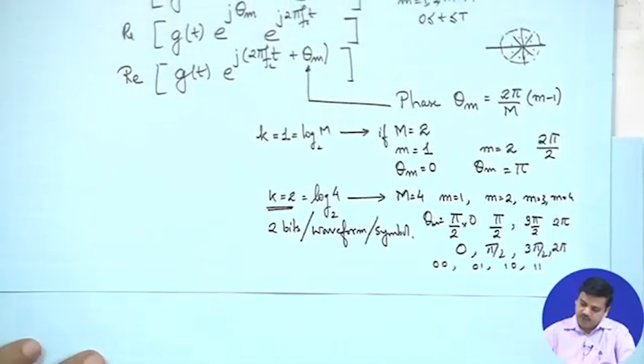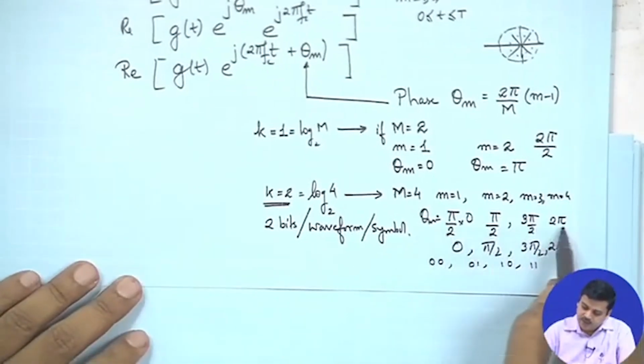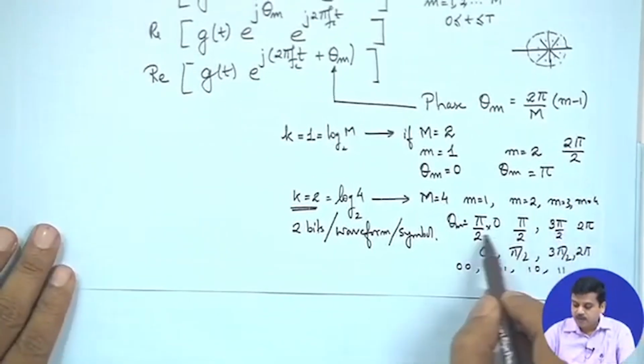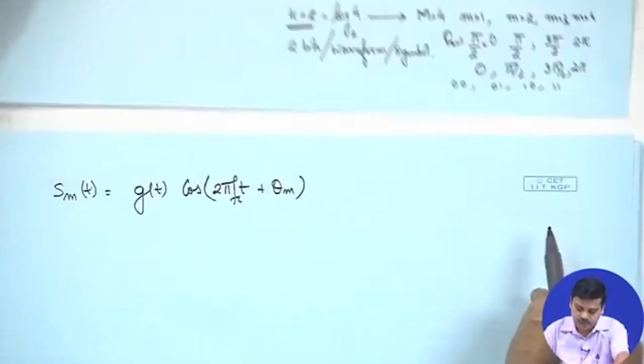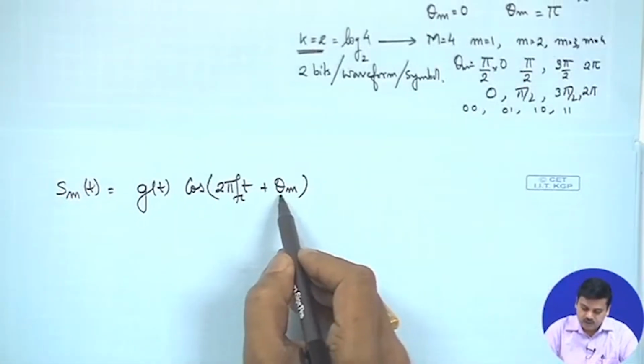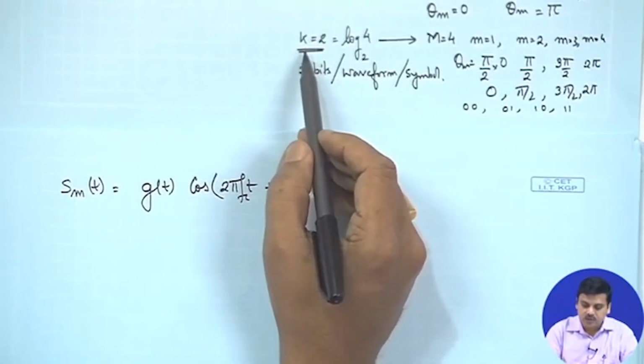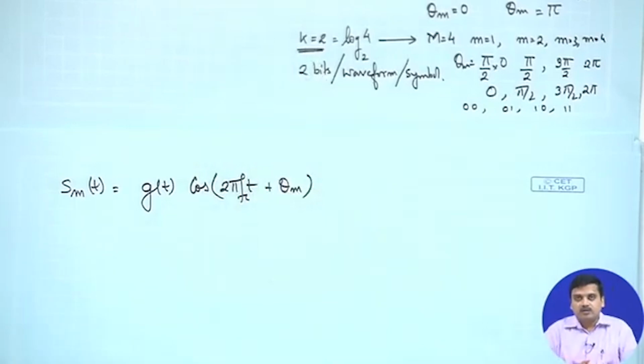That is what we have described here, that these are a few angles that are available, and as we said in digital communications, we are mainly interested in choosing one of the options. So, here is the same thing that you are doing, we are choosing this based on the bit sequence, right, and this bit sequence is an outcome of sampling the analog signal followed by quantization followed by source coding, and these bits or these levels have nothing to do with the levels of the quantization output. I repeat this statement once again.